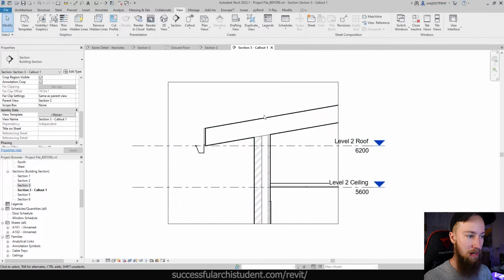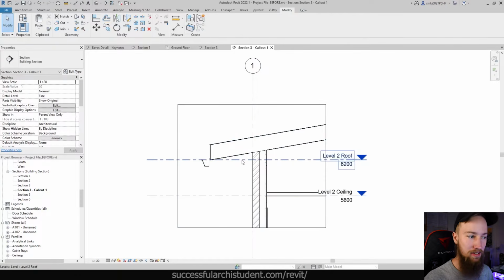Whereas if we go from medium to fine, it's not going to show anything extra in this drawing, but usually that would show things like door sections and the jamb sections of doors, the actual profile of, say, an aluminium window or something like that. But if we just put that to fine, that's going to show all the detail that's available to us, which is what we want.